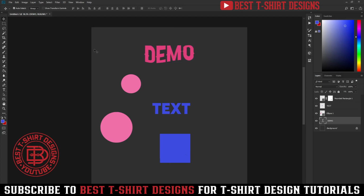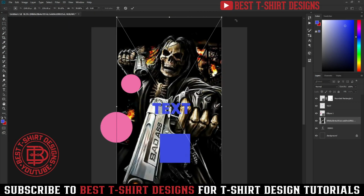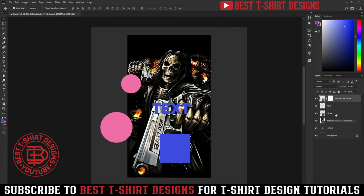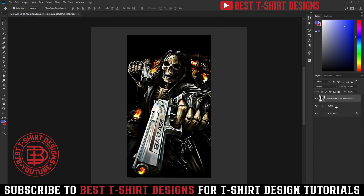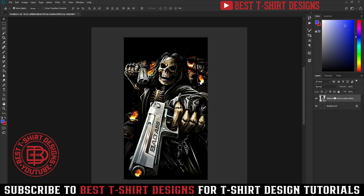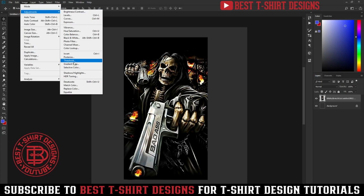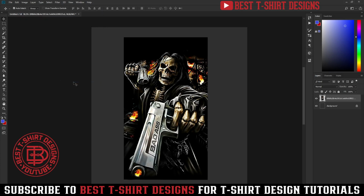And there is one more thing which we will do: we will need to bring images here. So let's erase everything that we created. Now this is our image. First step is we will rasterize it, and then once it is rasterized we have to go to image, then adjustment, and then desaturate. So desaturate will make it black and white.